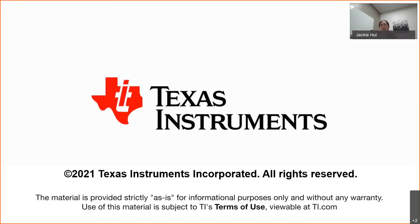But I also want to bring up that, as I showed you earlier during the presentation, the new architecture for the half-bridge driver actually opened up the possibility for us to support higher voltage half-bridge. It's still a challenge in terms of 1,000 volts, but we do have plans in the future to utilize this new architecture and support higher voltage than, say, 600 volts.